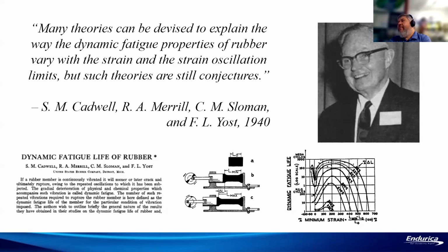But it's a big field, and it has a reputation because of rubber's nonlinearity, and because when you talk about fatigue or durability, you're really talking about very complex service conditions, right? In applications, a lot of times, not only do you have the nonlinear behavior of the rubber, but you also have multi-axial loading, right? Load inputs from many directions. You have variable amplitude loading, and there are time dependent effects and temperature effects and so on and so on and so on.